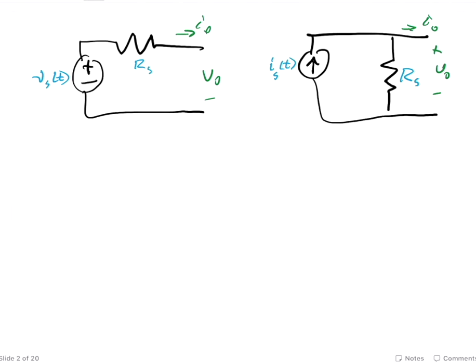However, a transistor is really a current source. It's a voltage-controlled current source. And so when we draw out circuits with transistors in them, they're likely to have a Norton circuit. But the thing that we're actually trying to make is a Thevenin circuit. So we're going back and forth all the time between them, and it needs to be really comfortable and easy for you to do that.